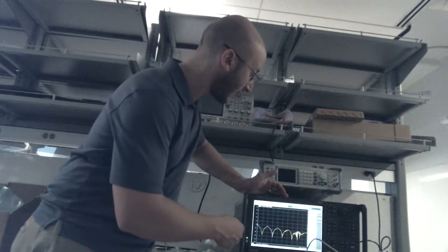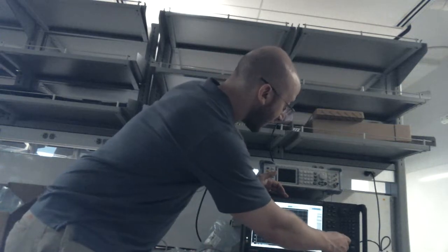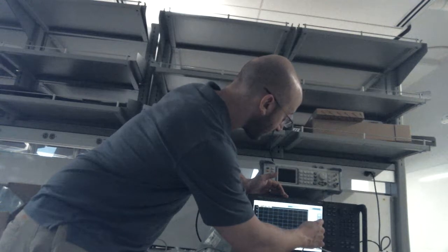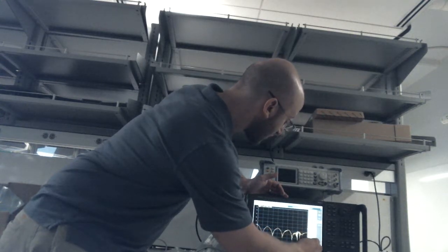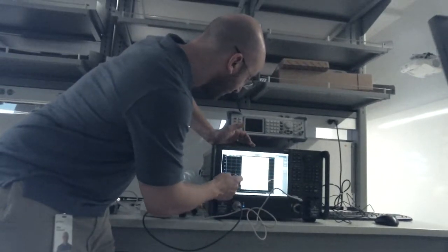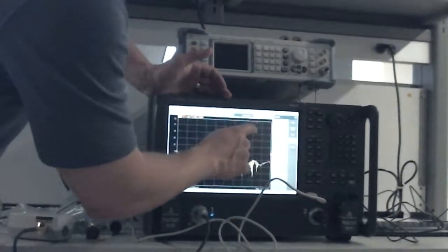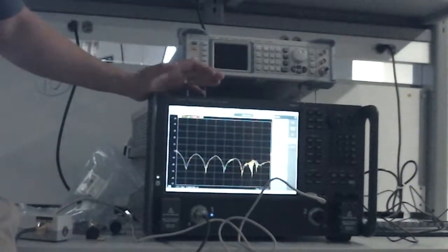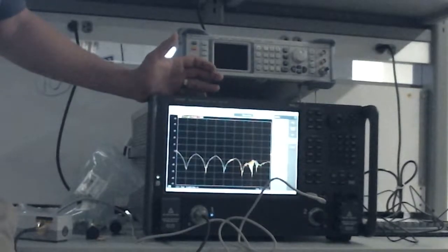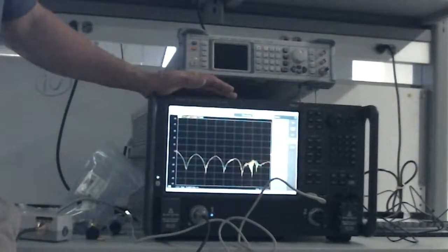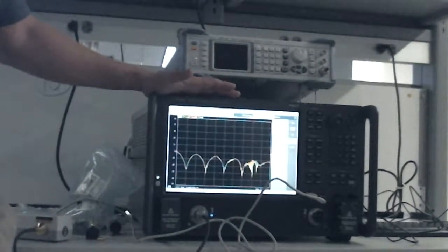And if I take a look at, again, one of the things that we can do really quickly is just take a look at the network analyzer that you guys have. And so you have the noise figure option and the internal noise receiver. And so that's all the options for noise. But what you can do is there's an option to add like a lot of attenuation inside.